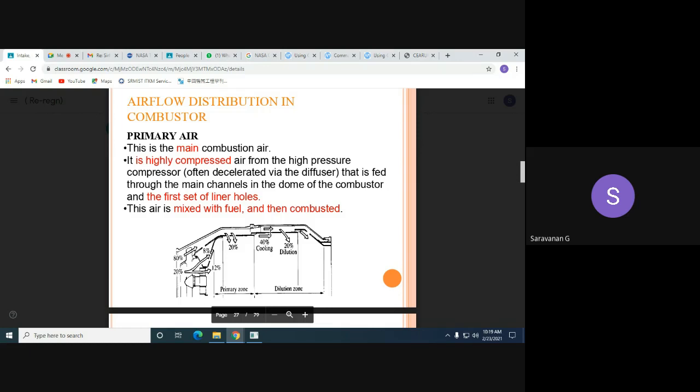So you can see the diagram. 80% of the airflow stream will flow to the side stream. That is split into three components: primary, secondary, and tertiary, as 20, 40, and 20. And the remaining 20% will be allowed to flow to the engine internally. That is split into two portions as 8% and 12%.